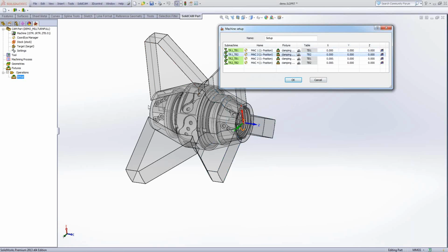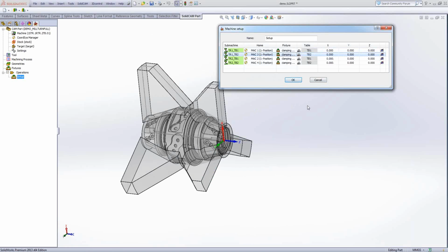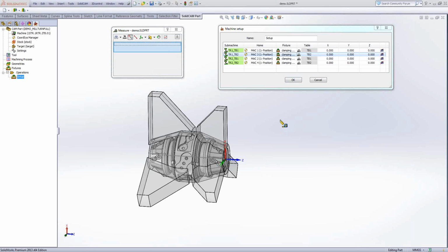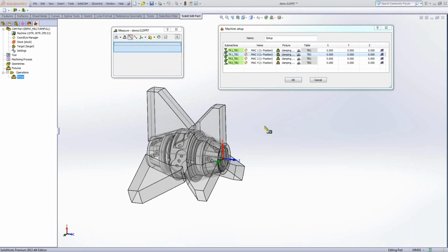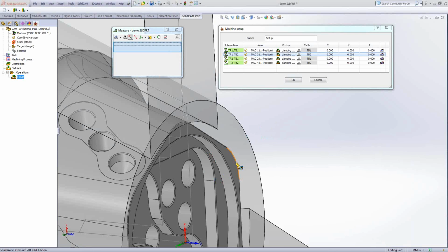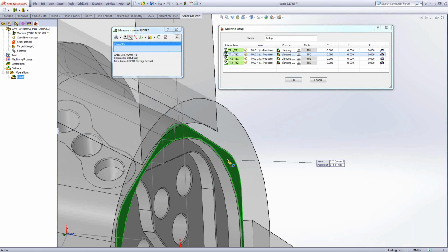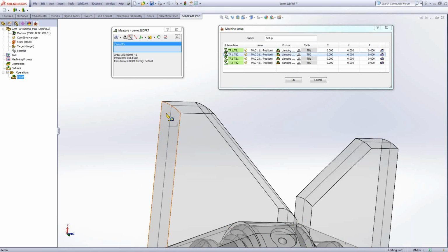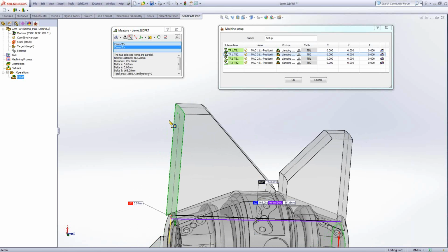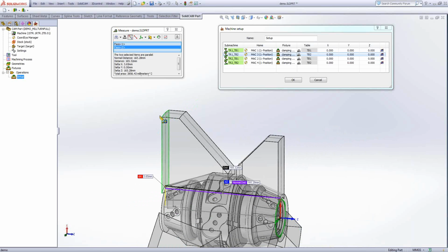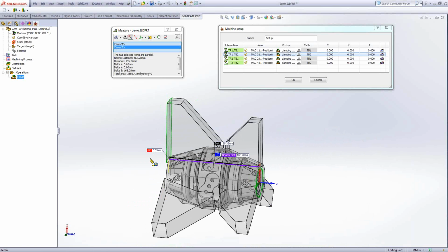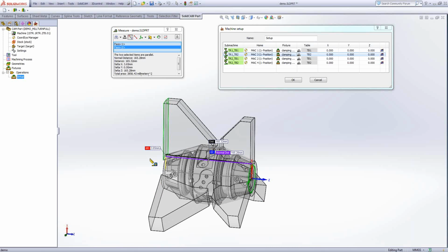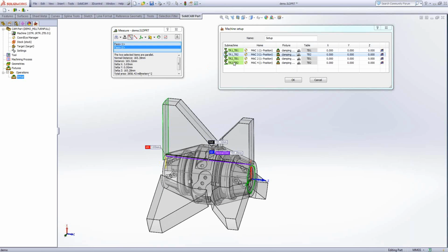And now we need to measure and position the coordinate system Mach 1 position 1 related to the submachine. So let's see, I will use the SolidWorks measure option from the face of the part to the back side of the fixture. Here, this fixture will be connected to the chuck. So my submachine is on the face of the chuck. I have 165.28.